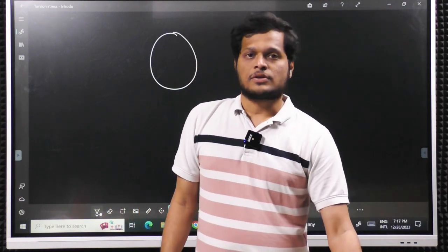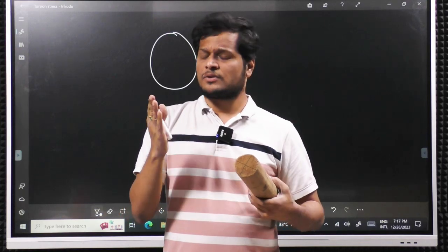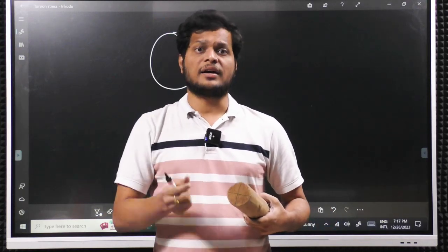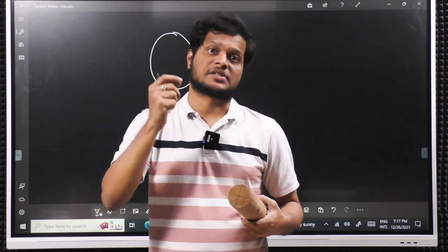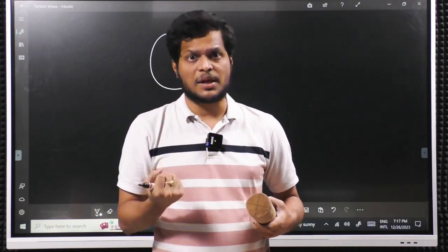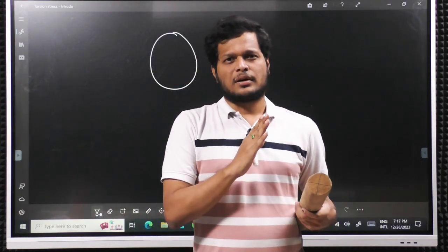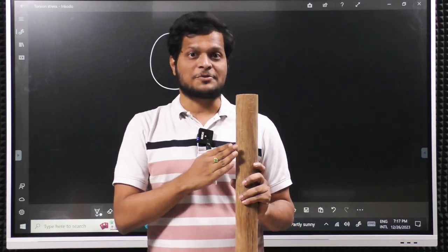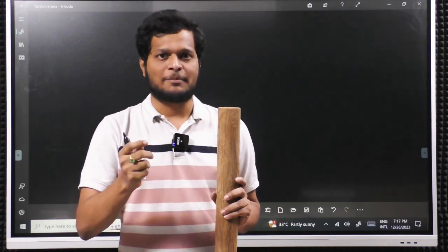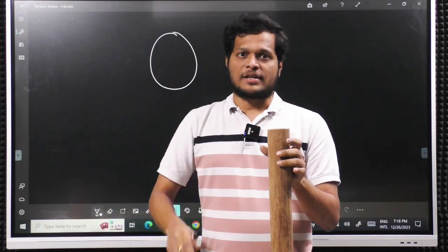Okay, so already we have seen circular shape. So circle to square: if you compare the area, circle requires 1.18 times. So around 18% extra area we require to get the same moment of resistance. So generally we don't use circular beams. Okay, for columns, circles we can use. Why? We will see in compression members. Okay, compression member topic.